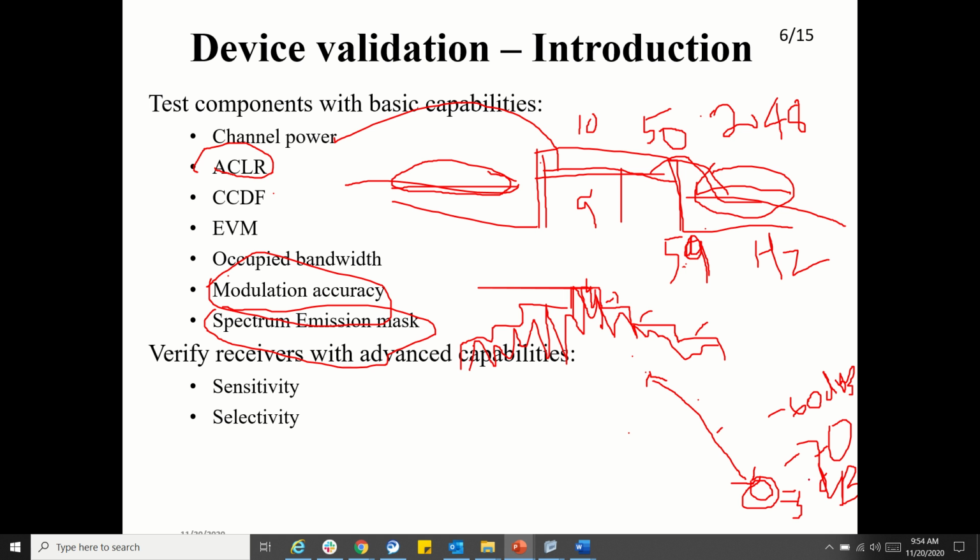So now what you will do is, if your receiver sensitivity is minus 60 dB alone, then it will only detect the noise, not the actual signal. If your device is sensitive to minus 100 dB, you are able to decode the signal, then you can catch and decode this signal successfully. So that is called sensitivity.